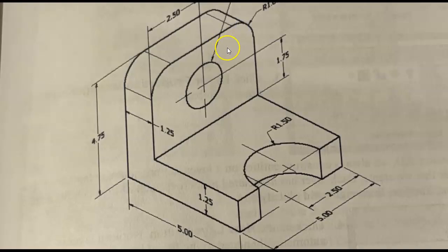We're going to start by activating the construction line layer and drawing this on the construction line. So let's just pick a point somewhere in the screen. Now notice I have zoomed in, so I'm pretty close to the origin point. If you are zoomed way out and you're getting really super large numbers showing up here, then you might want to zoom in a little bit.